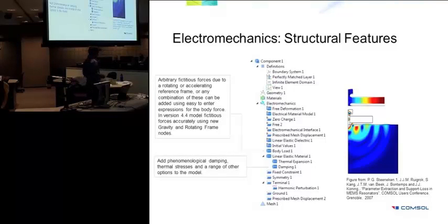You can model objects that are infinite in length or width or size, but you do not want to model the infinite size of that object. Therefore, you truncate the object and then model the rest of it using a special condition called perfectly matched layer, if you're doing a frequency domain analysis, meaning you're analyzing frequency response or you're calculating resonance frequency. This is also used to calculate quality factor.